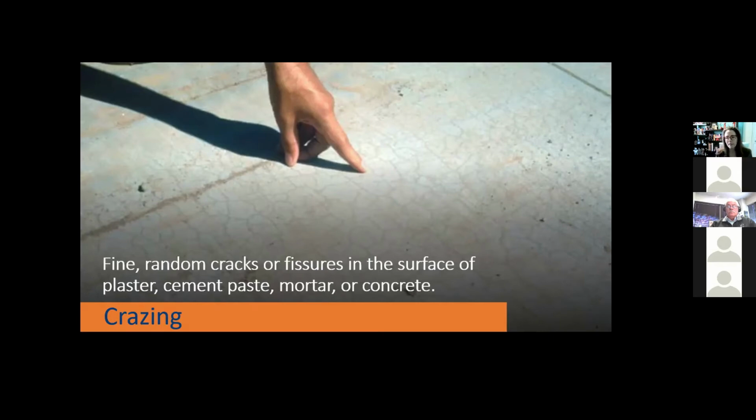So the question is, is this a blemish? In Florida, they pay money to have concrete look like this, but in the Midwest, our issue really is durability. Do we want scale resistance for freeze-thaw environments? So when you have a crazed surface, you have a network that's already prone to allow salt to soak into that cracked network. So what most repair strategists would encourage is for you to seal the surface. If you seal it, then you're going to slow the ingress of that salt attack and further scale and other issues.